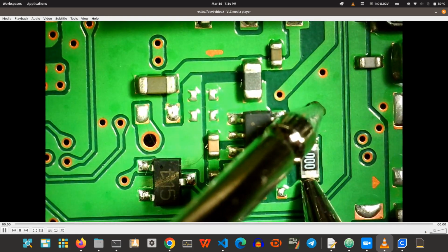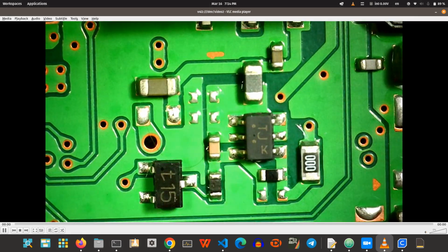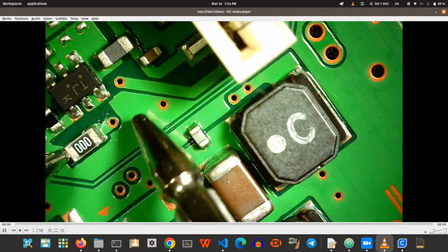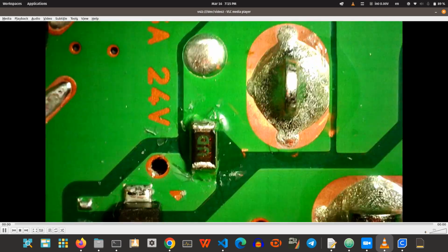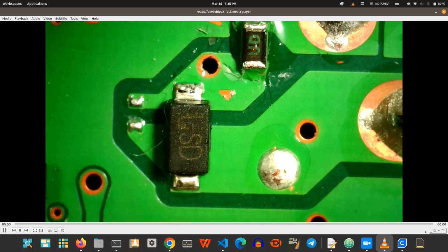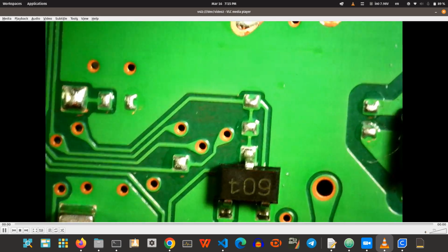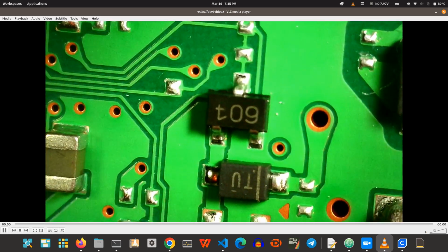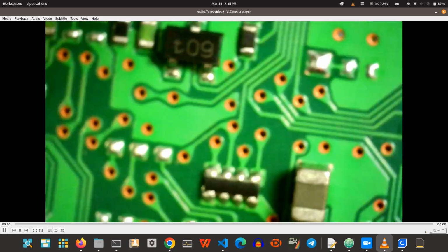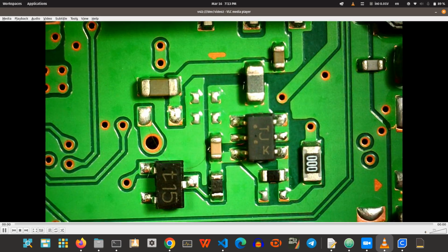The first suspicion line is the MOSFET line that feeds several inductors that work on the very high frequency. I will show the datasheet later. This one is input. Actually, it's 12-volt input that connects through the fuse and the Schottky diode. Then we can see the other components that distribute the power. So let's check this one first.